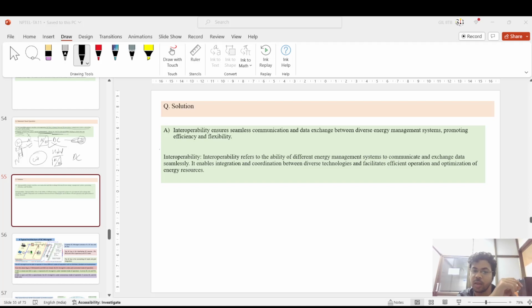The second thing is that PV is also connected in the system, but PV has a certain limit. In UP, they say that based on the meter you have taken for your home power consumption, suppose you have a 2 kilowatt rating meter, you can install only 30%, which means 30% of 2, so a 600 watt PV plant only.